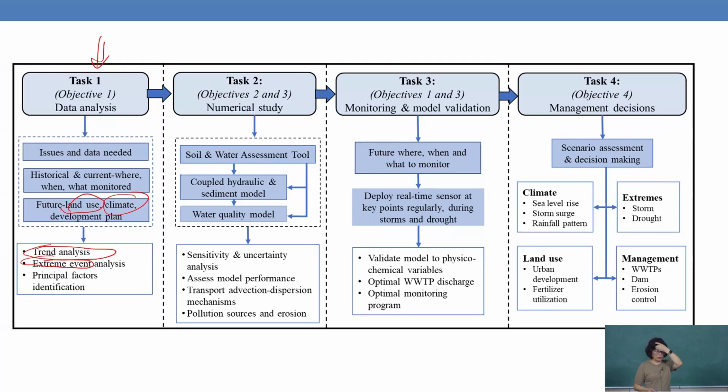Then we try to set up the model. For any catchment study, we need to have a good hydrological model before we do hydrodynamic. For the DHI model, I think a NAM is embedded, so we can use those built-in hydrological models in DHI.